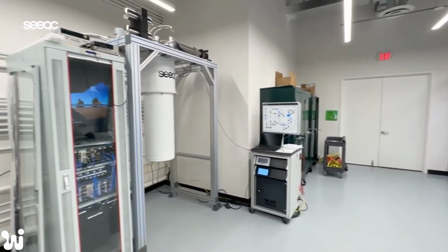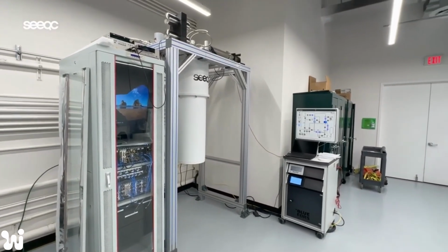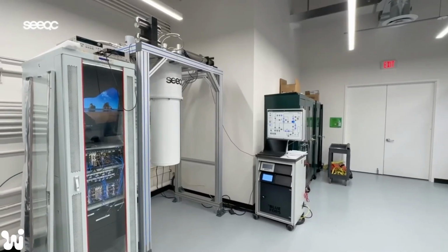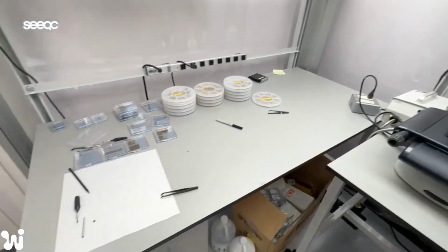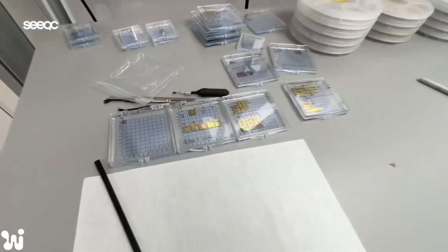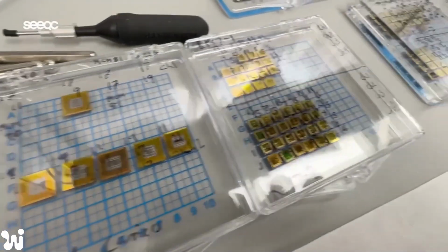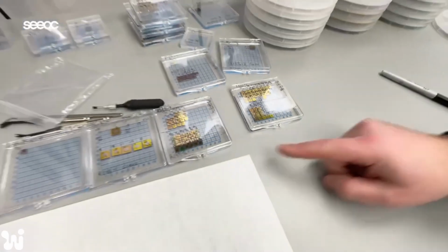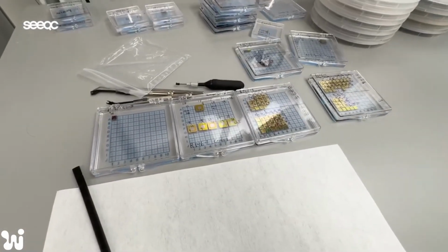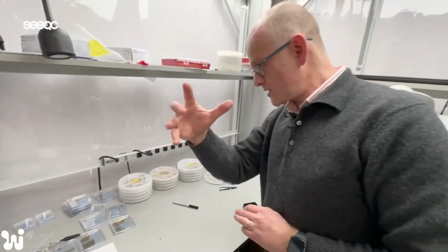Here we're testing our 5-qubit quantum computer, which is being tested right now, again, remotely by people. All these tests are being run from England. Like I mentioned, chips were fabricated across the street and then brought here already diced. Usually we have chips in different form factors, either 5 by 5 millimeter chips, which are smaller, or 10 by 10 millimeter chips, which are bigger. For these different chips, we have different packages, different immersion probes, and different packages for millikelvin.